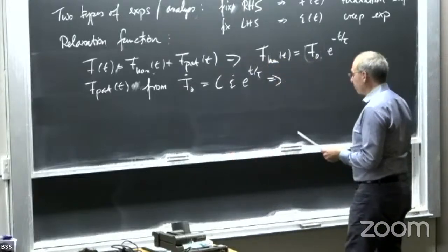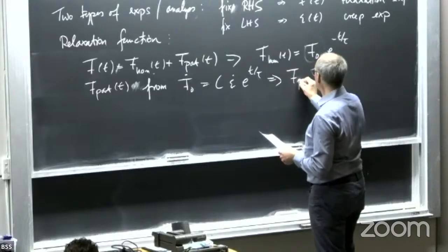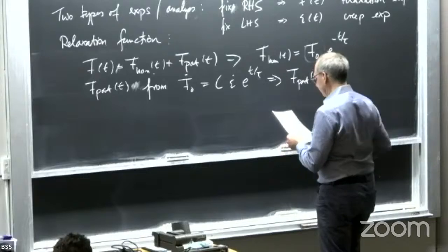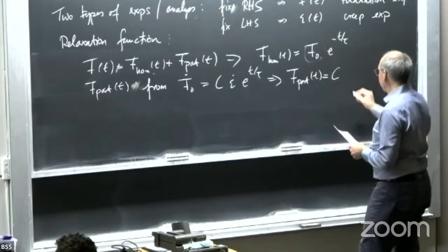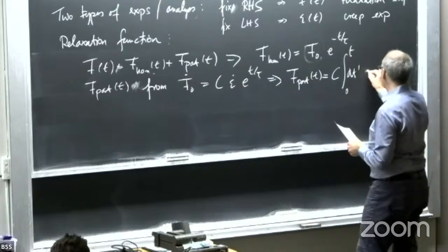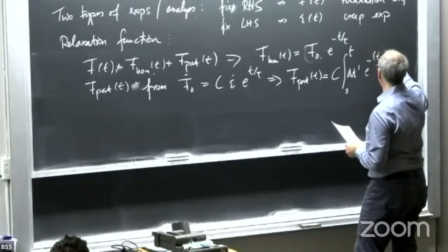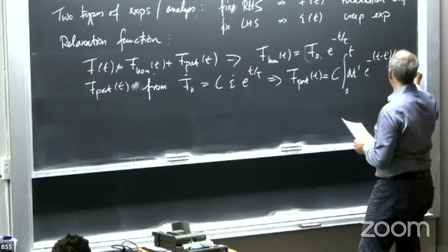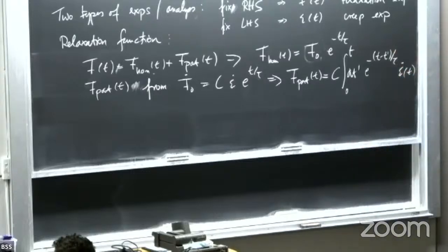And then you can integrate this up. And the particular solution will be an integral. It goes with the elastic constant, integral over some auxiliary variable from 0 to t, e to the minus t dash divided by tau times epsilon dot at some time t. Okay, so these are the kind of equations which are called linear Maxwell-Boltzmann or something like this. Okay, so this is the theory of viscoelasticity. So this is basically a kernel which you have to integrate.